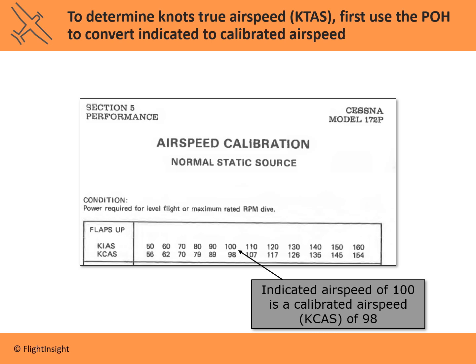What we're looking at here is also in Section 5 of the POH, and it's a calibration page. If you take a certain indicated airspeed, what the airspeed indicator is actually telling you, you need to be aware that it needs to be calibrated for errors in the altimeter or the pitot-static system. Basically, the slower you get, the more these errors start to manifest because of uneven pressure differentials in the pitot or the side of the aircraft or things like that.